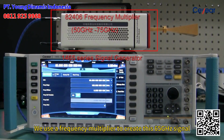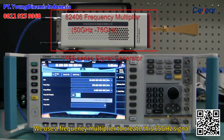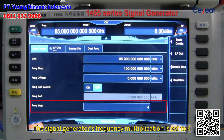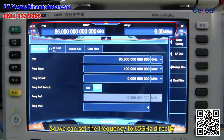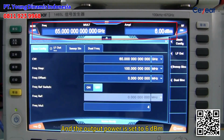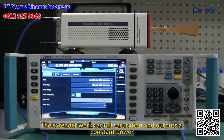We use a frequency multiplier to create this 65 GHz signal. The signal generator's frequency multiplication is set to 4. So we can set the frequency to 65 GHz directly, and the output power is set to 6 dBm. The extender works at full saturation and outputs a constant power.